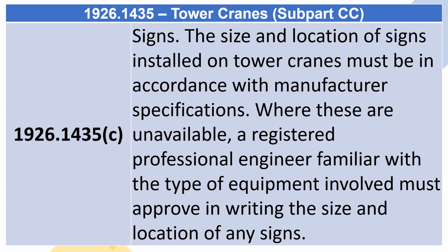1926.1435(c) Signs. The size and location of signs installed on tower cranes must be in accordance with manufacturer specifications. Where these are unavailable, a registered professional engineer familiar with the type of equipment involved must approve in writing the size and location of any signs.